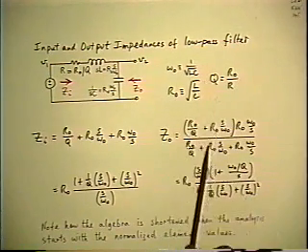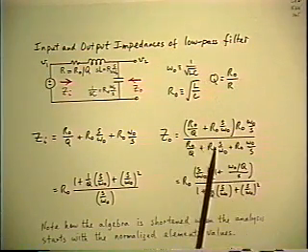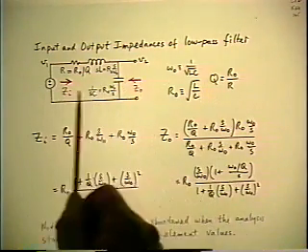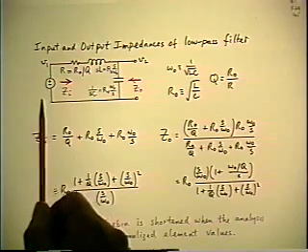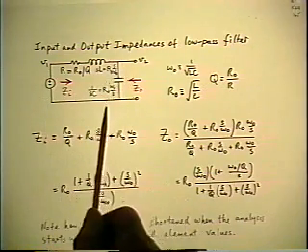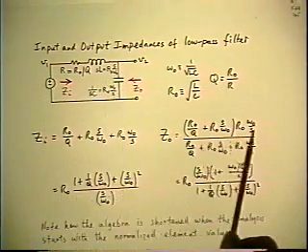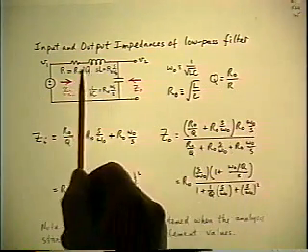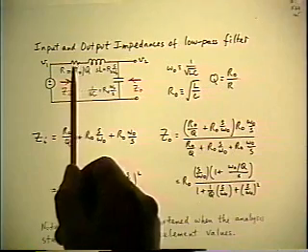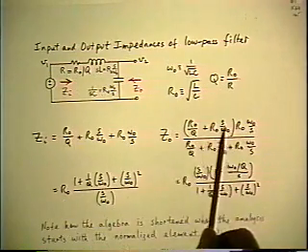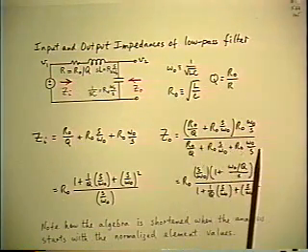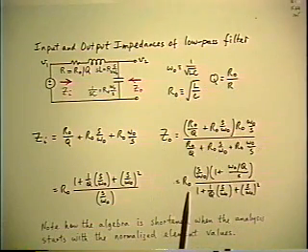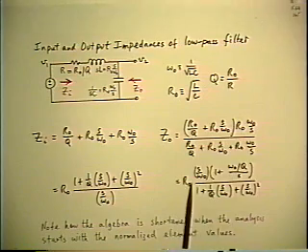And the same thing with the output impedance. Output impedance calculated by looking in at the output with V1 at 0. So it's the parallel combination of the capacitor, which is R0 omega 0 over s, and the resistor and inductor in series. So that's product over sum. And once again, the R0 shows up immediately as a multiplier in front.